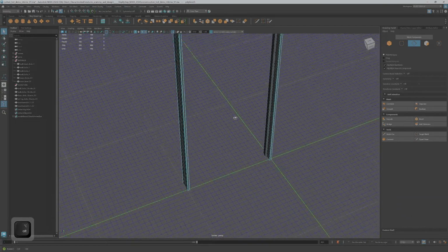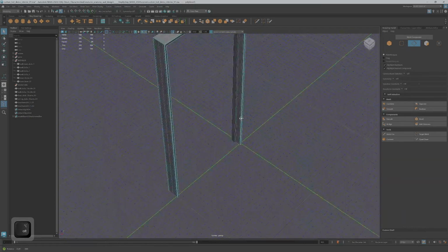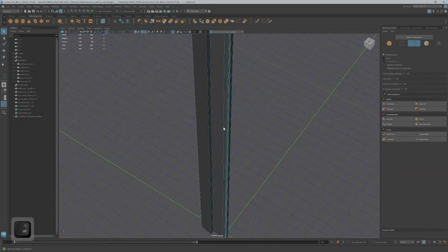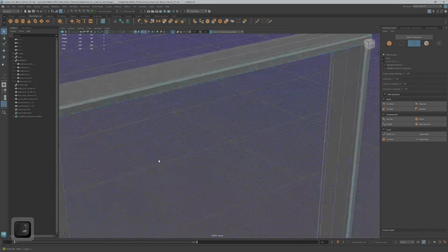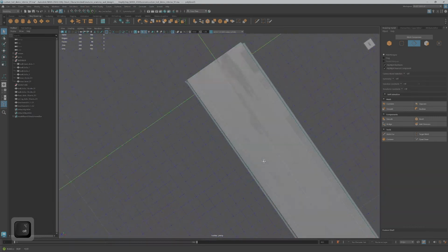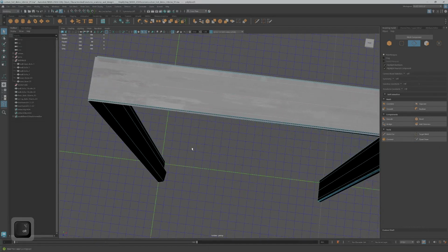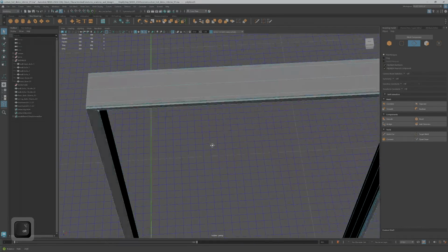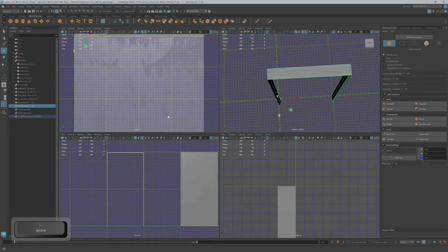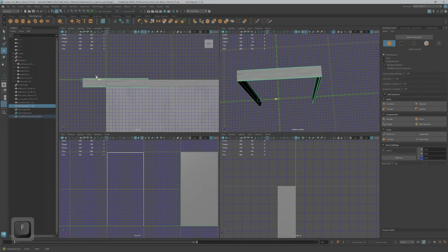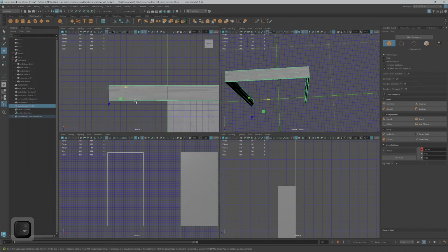Okay, let's hit Q on the keyboard, back to selecting, and yep, everything's looking okay. Looks like I might have accidentally grabbed a face over here on this side. What did I do? Don't know. Okay, well, there's a couple things we can do here. We can use the symmetry tool, so I'll just drag this over on the top, making sure it's at the halfway mark in between.